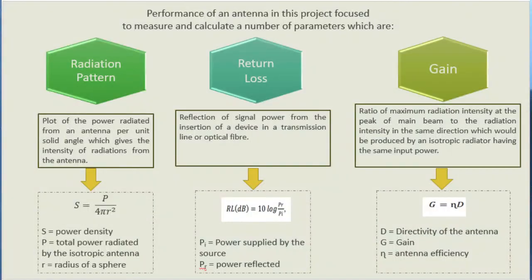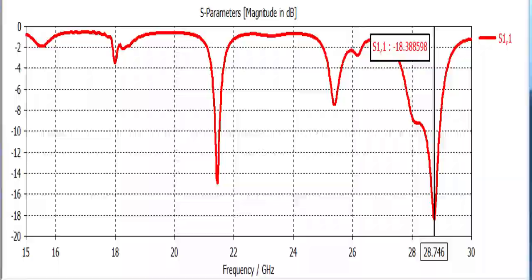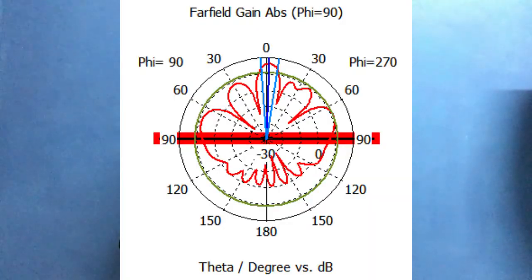In conclusion, during designing and selecting the best antenna design, some parameters have been chosen as indicators such as isotropic gain, return loss, and also radiation pattern. This research concluded the 4 times 4 array antenna design which replicates the intercon design is the best design suited and answered the objective by having high gain, less return loss, and a focused and better radiation pattern.